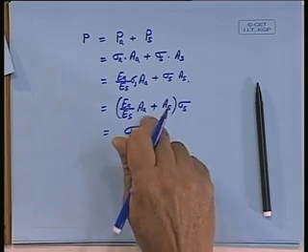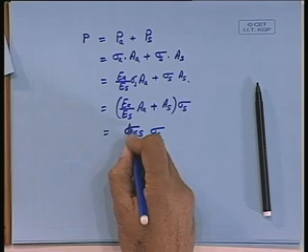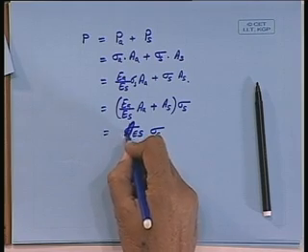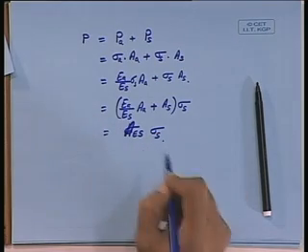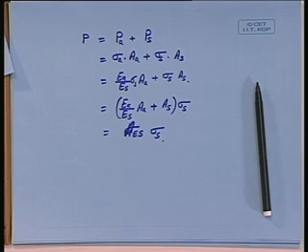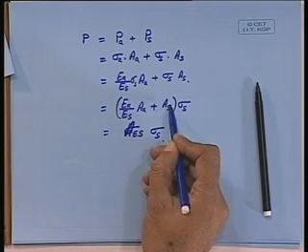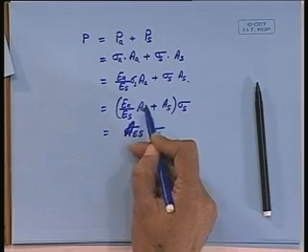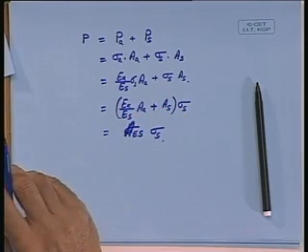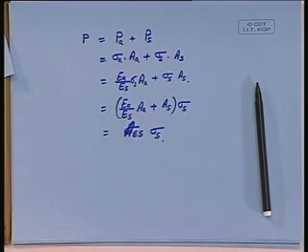Sorry, not sigma equal, area equivalent steel. Now, what is this area equivalent steel? Area equivalent steel is area of steel plus area of aluminium converted to steel with this ratio.